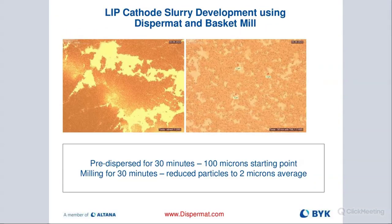And then again, with that milling system, this is another example of the efficiency of a basket mill. We pre-dispersed this material. It was an LIP cathode slurry, and we pre-dispersed for about 30 minutes. We started with 100 microns of particle size, and we milled that down for about 30 minutes using a TML, and we were able to go down to 2 microns average particle size with a standard TML basket mill.